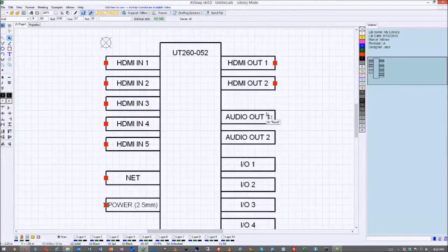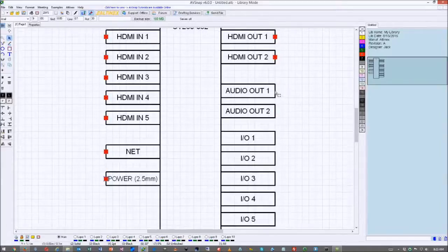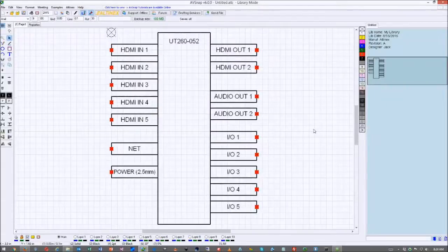So we can repeat the same thing for all of the other connectors. I'm just going to put the snap points here. They're empty, there's nothing there, and I'm going to show you how to adjust them once we get into design. So here's all of our snap points. Our symbol is ready. The only thing we need to do is go to properties now.